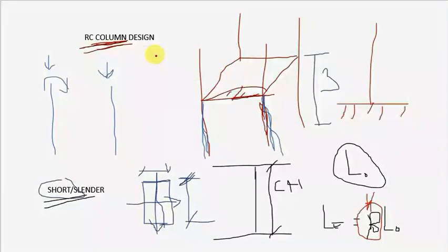Most of the time our structures are really unbraced, because most of these structures don't have a shear wall, and therefore they're not braced. They're sway frames. So you have to really know and pick the right value for beta. Let me just speak a little bit about this beta. I think it is very important.